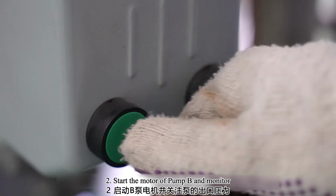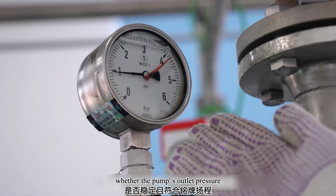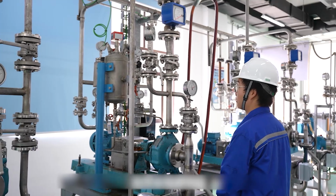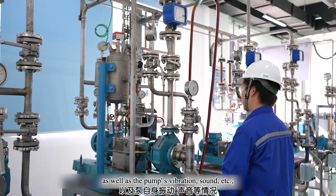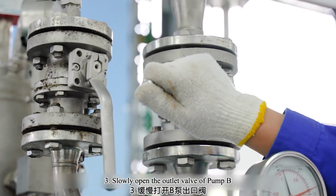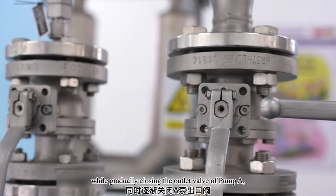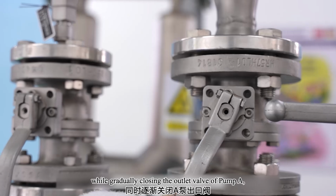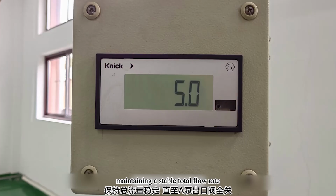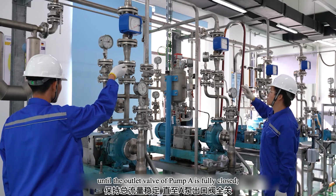Second, start the motor of pump B and monitor whether the pump's outlet pressure is stable and meets the nameplate head, as well as the pump's vibration, sound, etc. Third, slowly open the outlet valve of pump B while gradually closing the outlet valve of pump A, maintaining a stable total flow rate until the outlet valve of pump A is fully closed.